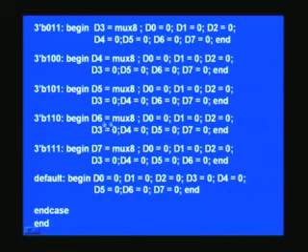Finally, when there was a case, a corresponding end case must be there, and since we put a begin for the beginning of the block, there must also be an end. If you forget any of this, including semicolons, the error message promptly comes while compiling.